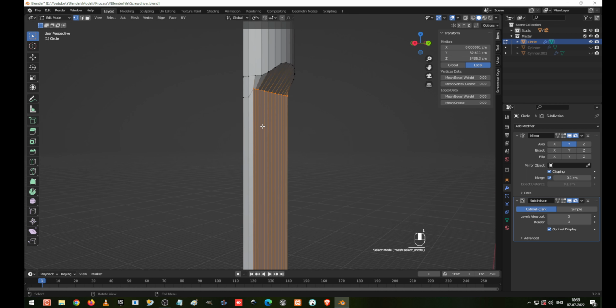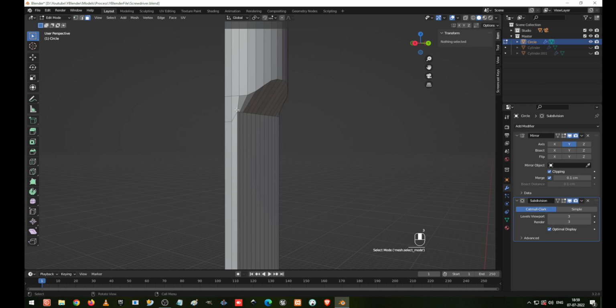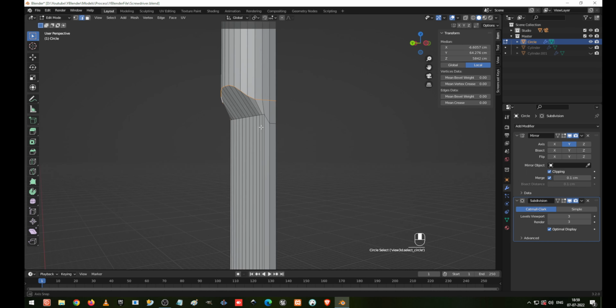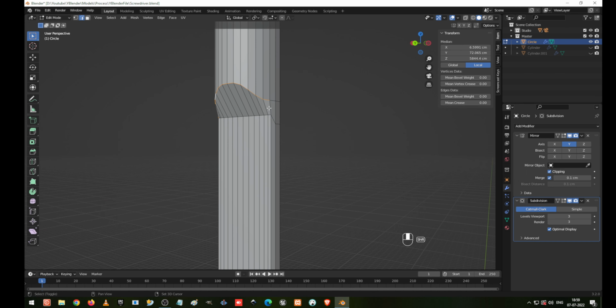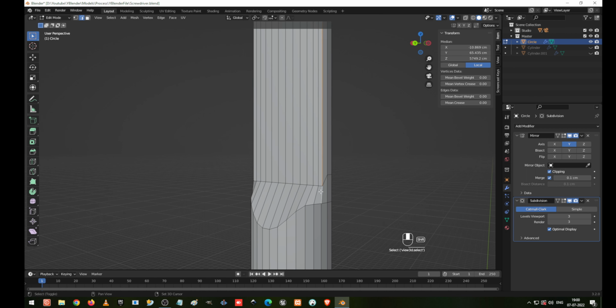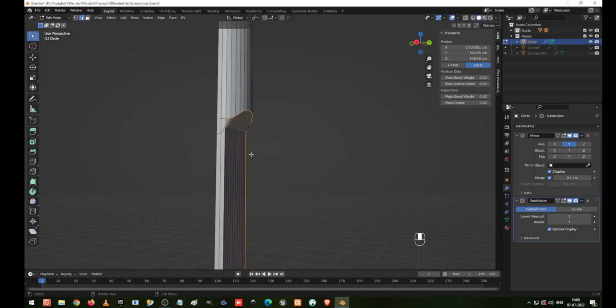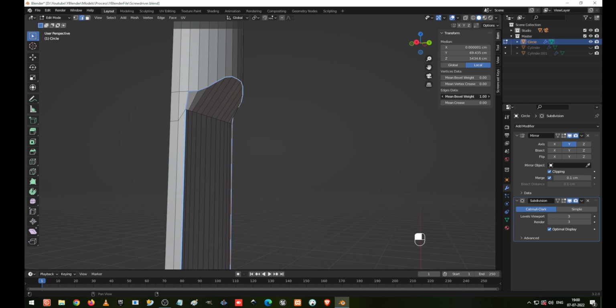Now I press, go to the edge selection, I'm going to select everything, and middle mouse to unselect it the same. So after selecting these things, I'm going to give the bevel weight for this, make it 1, and add a bevel modifier.